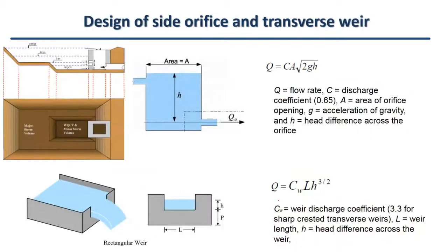And so if you're going to design a storage unit, or detention pond in this case, you need to pay attention to some things when you have an outlet. Here we have number 1, number 2, number 3, number 4 outlets. The first 3 outlets are called orifice. Okay, orifice has got this formula, and the 4th outlet is called weir. Okay, weir has got this capacity. This is the weir, and this is the orifice.